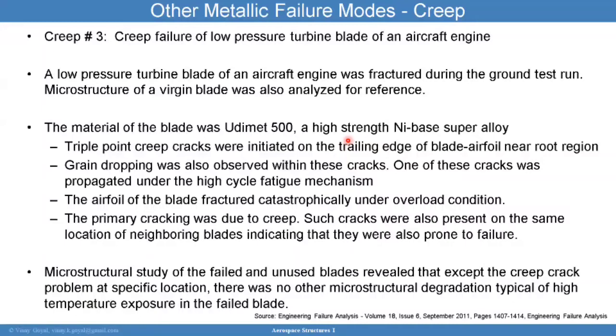And when they looked carefully, there was this triple point creep crack where a crack had initiated on the trailing edge of the blade airfoil near the root region.